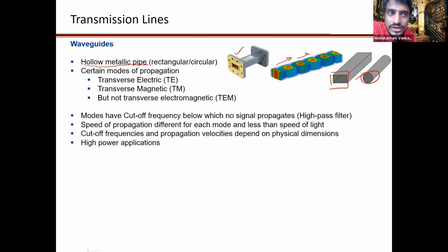It has certain mode characteristics of how the electric and magnetic field modes are. They are TE and TM modes, but here you're going to be looking at a different kind of transmission line that only supports the transverse electromagnetic mode. We will see that in a moment.